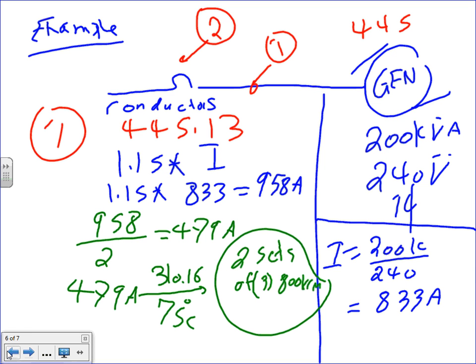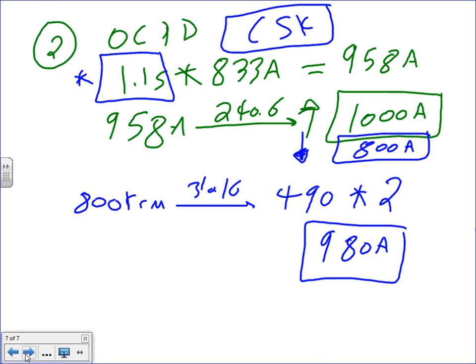If you look at the overcurrent protection device, at article 445.12(A): constant voltage generators, except AC generator exciters, shall be protected from overload by inherent design, circuit breakers, fuses, protective relays, or other identified overcurrent protection device suitable for the condition of use. It doesn't tell you how high you can go, and it doesn't tell you how to size it.